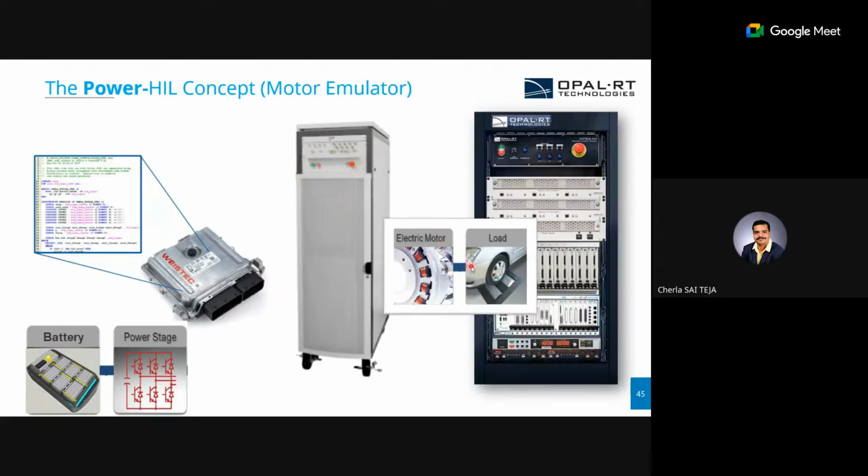Whatever motor characteristics we want, we'll first simulate them on the OPAL-RT system, take out those motor characteristics, and feed them to this motor emulator. These emulators range from a few kilowatts, starting from 60 kilowatt, and can go up to 500 kilowatt. The output of this power-level motor will be connected to the traction inverter, and the output of the traction inverter will drive this motor. In this way, you can validate whether your traction inverter is working fine or not in a safer environment. This is a PHIL solution for electric vehicle application.